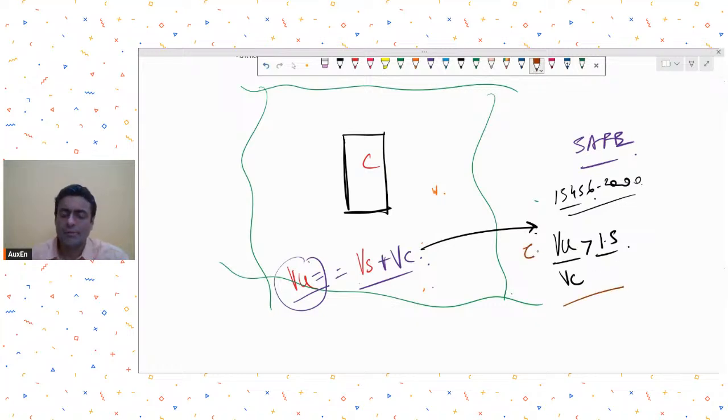It does not talk in terms of shear, it talks in terms of stress levels. So if the shear stress exceeds the concrete stress capacity by more than 1.5, then revise the slab thickness or raft thickness. No amount of punching reinforcement will be sufficient.